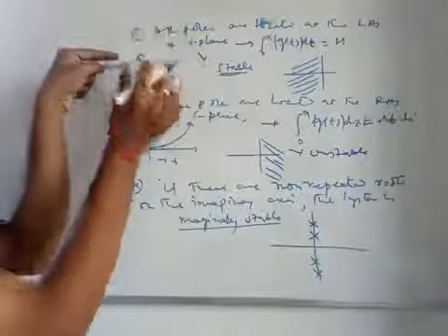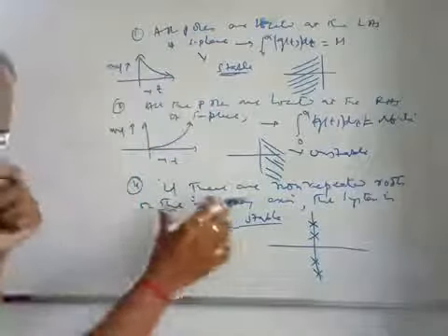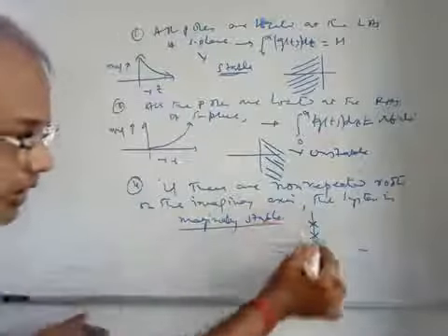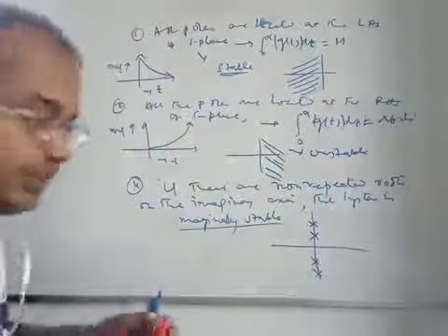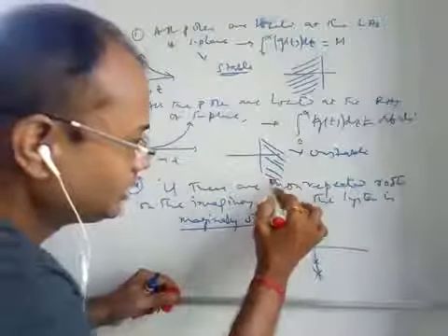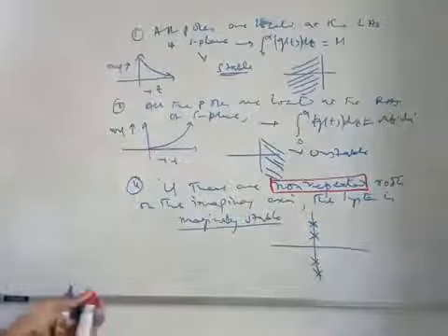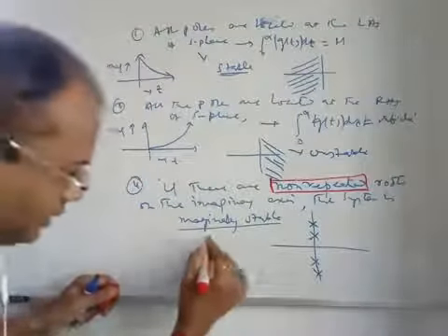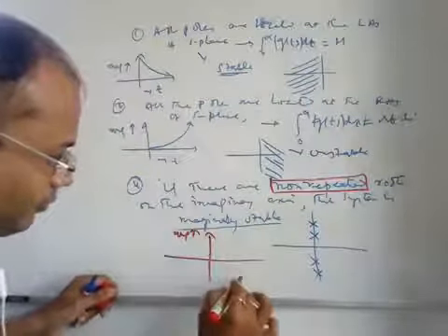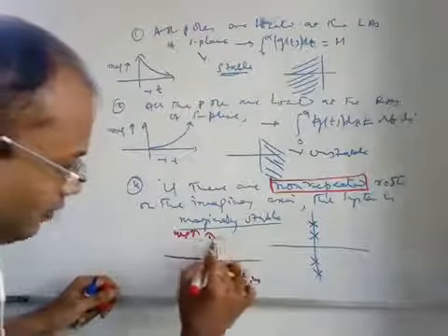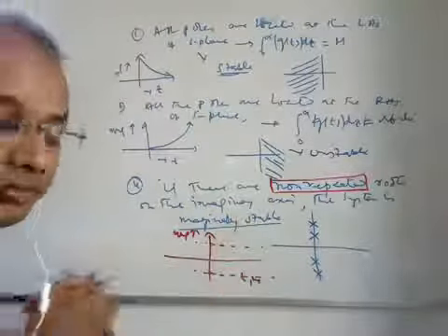This is the finiteness, and you see this magnitude is decreasing with time. What about the marginally stable case? If the poles are lying on the imaginary axis, but they are definitely non-repeated in nature, in that case what happens? Its magnitude is bounded, but not decreasing with time.